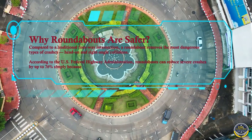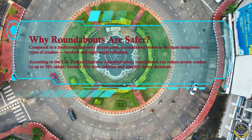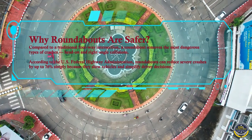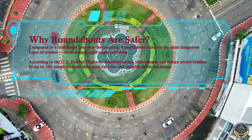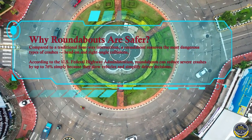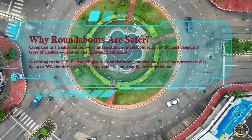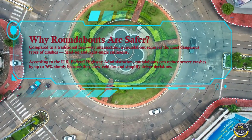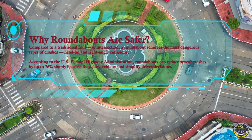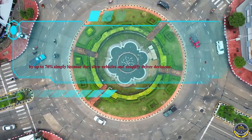Why are roundabouts safer? Compared to a traditional four-way intersection, a roundabout removes the most dangerous types of crashes, head-on and right-angle collisions. According to the US Federal Highway Administration, roundabouts can reduce severe crashes by up to 76% simply because they slow vehicles and simplify driver decisions.